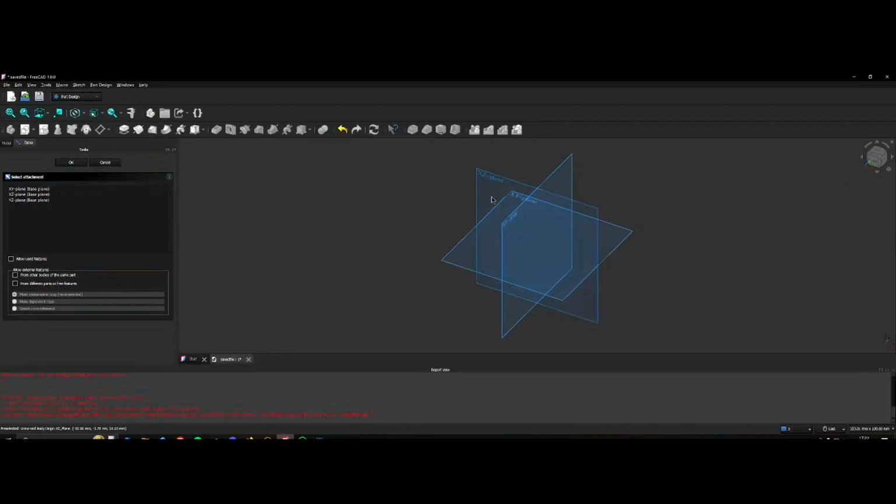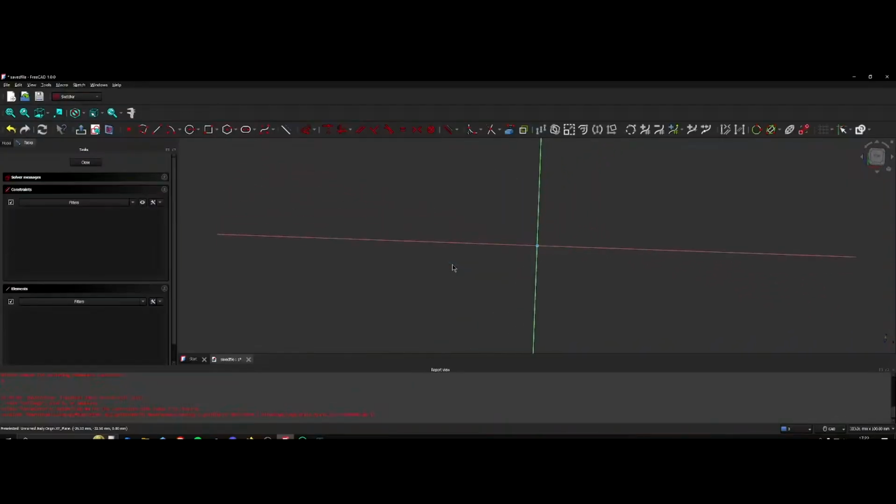When you create your first sketch in a project, you'll be asked which axis you want to base it off of. I mostly use the XY plane, but it doesn't matter too much for basic things. After you've selected an axis, your view will change from the 3D view you were greeted with at the start to a 2D coordinate plane. Additionally, you'll be moved automatically into the Sketcher Workbench if not already.